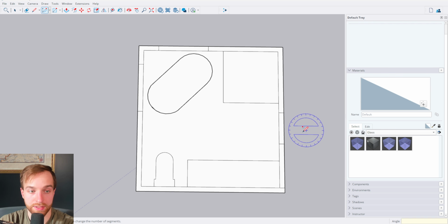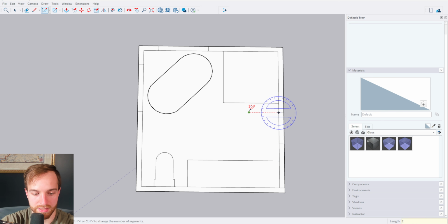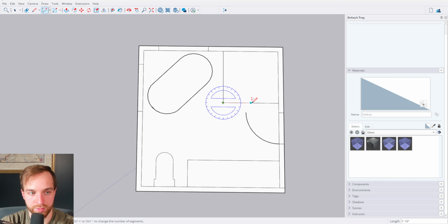So drop it in. Let's say I want to make the swing for the door here for both the shower as well as the bathroom entry door. I can go up here to the arc tool and I can just kind of select this. This was a 26-inch door, so I know we can come out 26 inches and then just finish the arc. And then same thing here for the shower door, right? We're going to do a 24-inch door, let's say, and we'll have it be an in swing. Or maybe we can also experiment, right? We have an outswing like that. For now, we'll just kind of do an in swing.